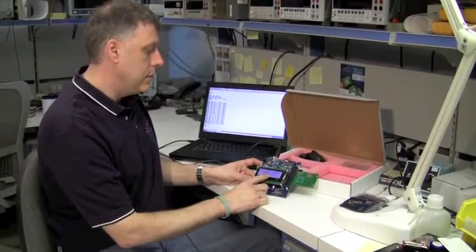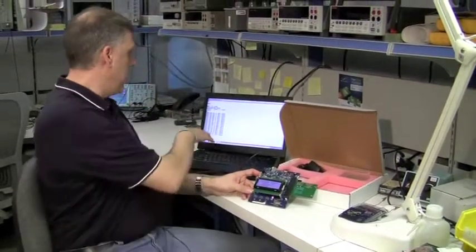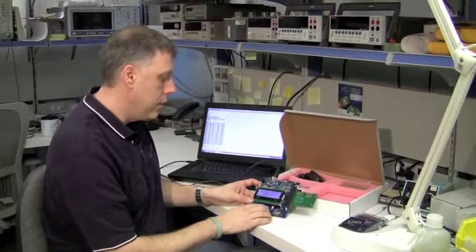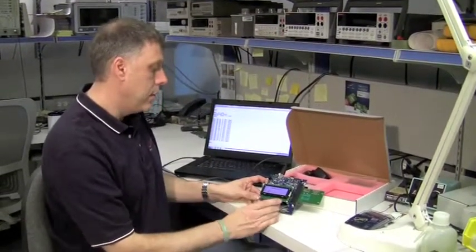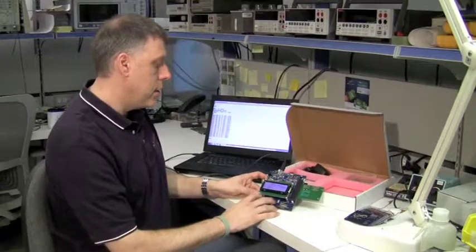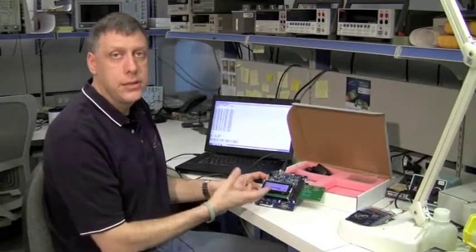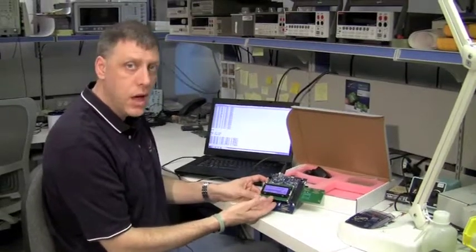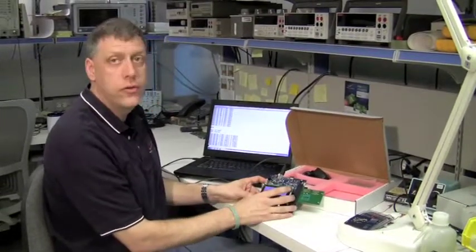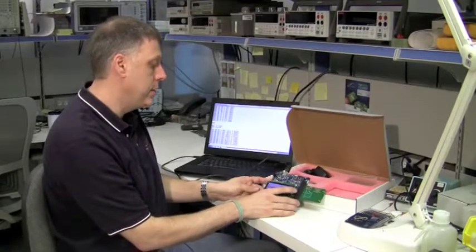So it has exited the discharge mode, and you can see up here on the screen it has produced an end, and then I'll proceed, and now it will ask me if I want to recharge. So I'll press A, start, and now the ADP kit has its own built-in charge source. It's supplying 4.1 volts, which is the nominal accepted standard charge value that we recommend for our microenergy cells.